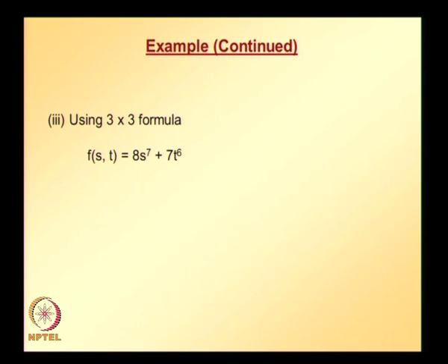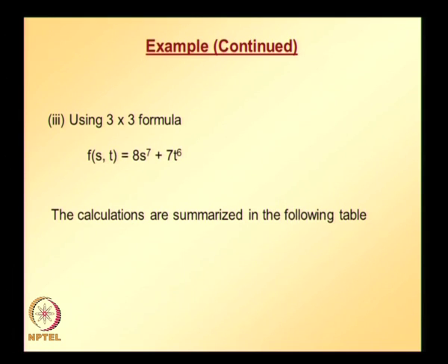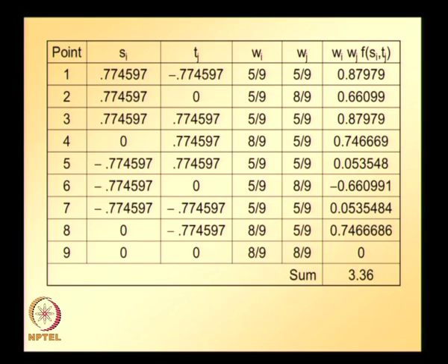So the function is shown here. So we are trying to use 3 points along s direction, 3 points along t direction. So similar to the previous case, the calculations are summarized in a tabular format. There are total 9 integration points, corresponding s values, t values are given, corresponding weights are given.